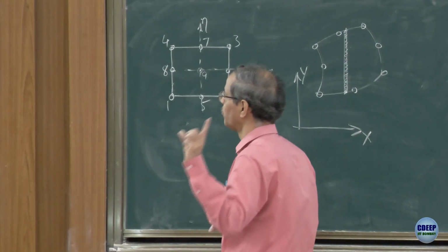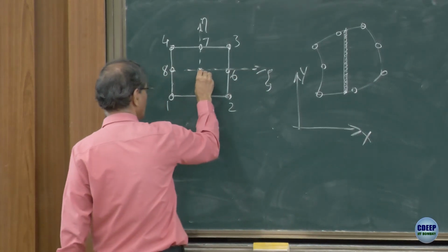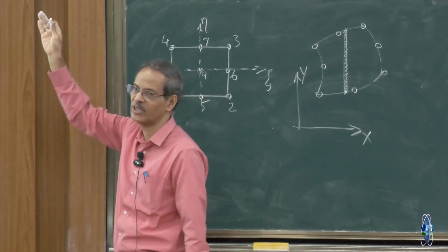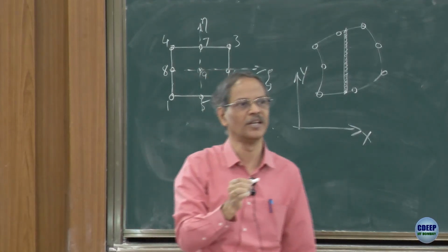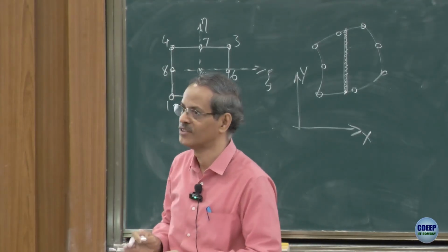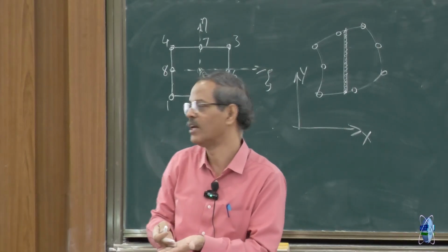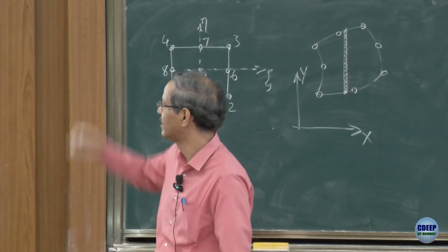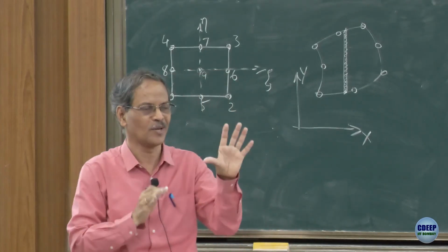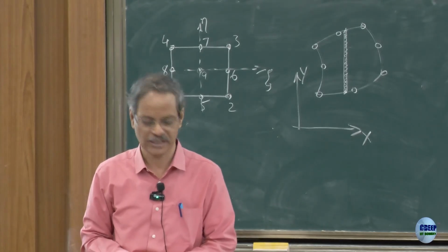You had done one single point rule for zeta, eta coordinates at 0. For the triangle, it is 1/3, 1/3, 1/3. That is the centroid of the triangle. When you are evaluating using the 1 point rule, you evaluate the function at the centroid and multiply by the weight as 1. So it is constant throughout the triangular domain. That is the value of the integral you will get. Like that, it has been developed. So these are implemented for triangular elements. Once you understand the concept, then you can figure out how the numerical integration is done.